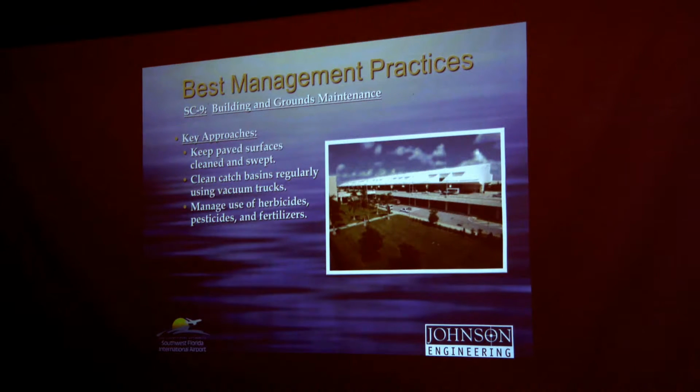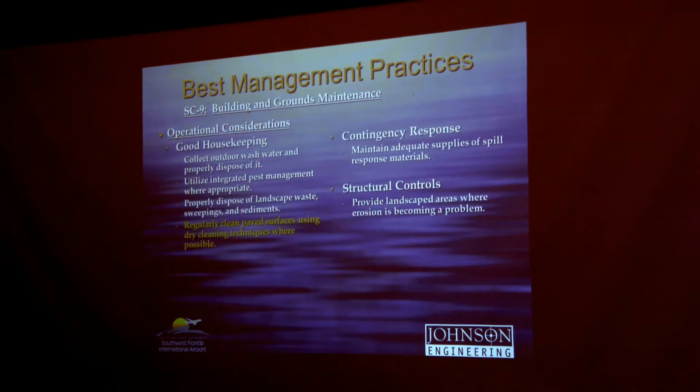SC9 is building and grounds maintenance. Key approaches here include keeping the paved surfaces clean and swept, clean the catch basins regularly, and manage the use of herbicides and pesticides. Operational considerations also include collecting outdoor wash water and disposing of it properly, utilize integrated pest management systems where you can, properly dispose of landscape waste, sweepings, and sediments, and maintain adequate supplies of spill response materials.